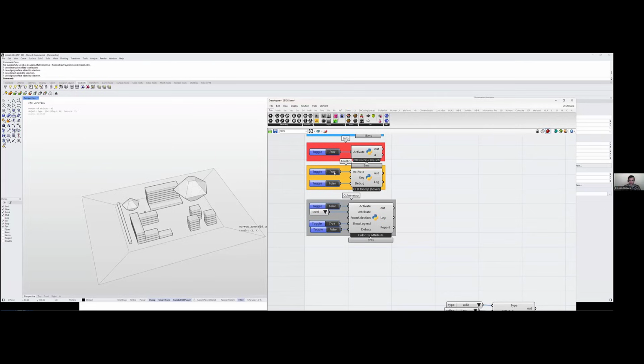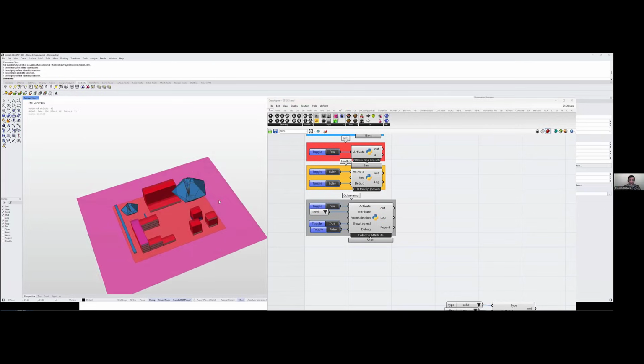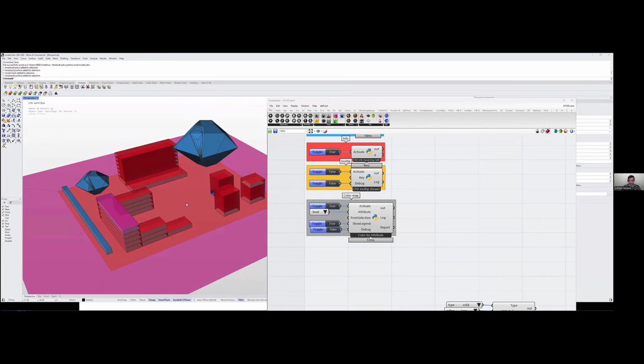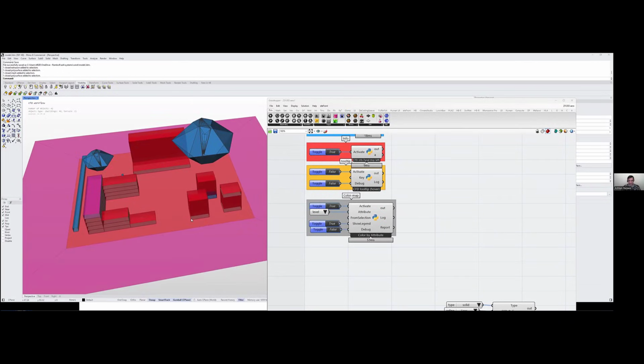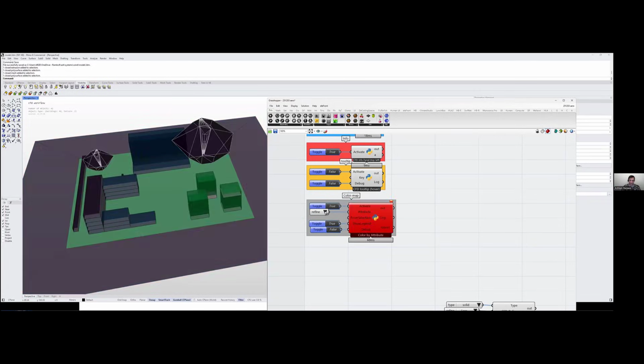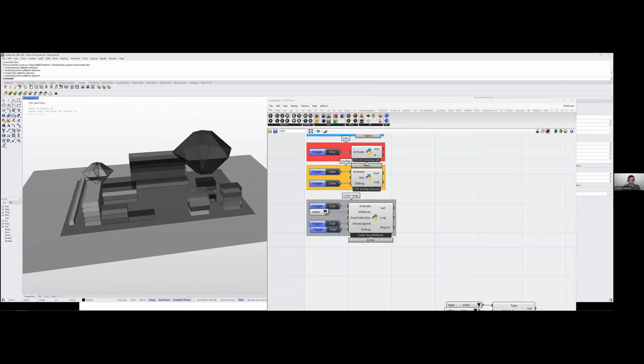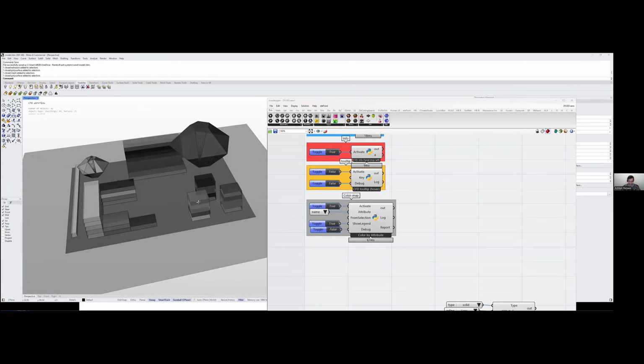And you get to also see if you have different levels. You can filter them out, and you can color map your object based on the values or attributes that you gave to your objects in the key value pairs. And this is based on the values. I know that the ones that have the same color are going to be tessellated in the same way. And you can do it with types. You can do it with refinement. I got some error, probably runtime error. You can also have it with names, which is useless in this case, but just for demonstration purposes.